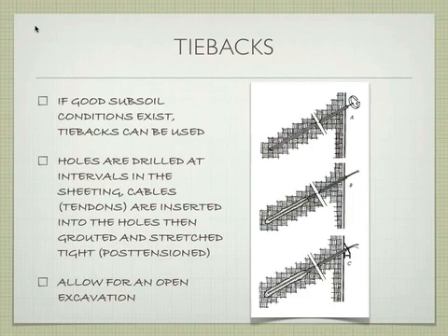And then you're going to use a specialized hydraulic jack that's going to put those cables into severe tension. And then you're going to insert this little block on the wall that holds that tension when you release the cables. Okay, and it's going to press that wall in. Does that make sense? So you've got this really taut tension cable with the grout at the end. There's your little piece. So this is all that's protruding out into the excavation of the site. There's no braces, there's nothing else. So this is the excavation area here.